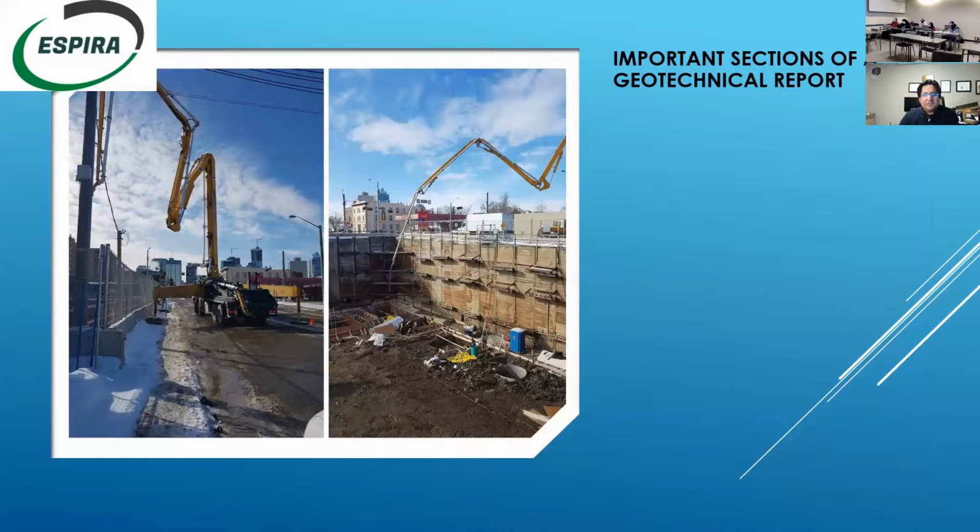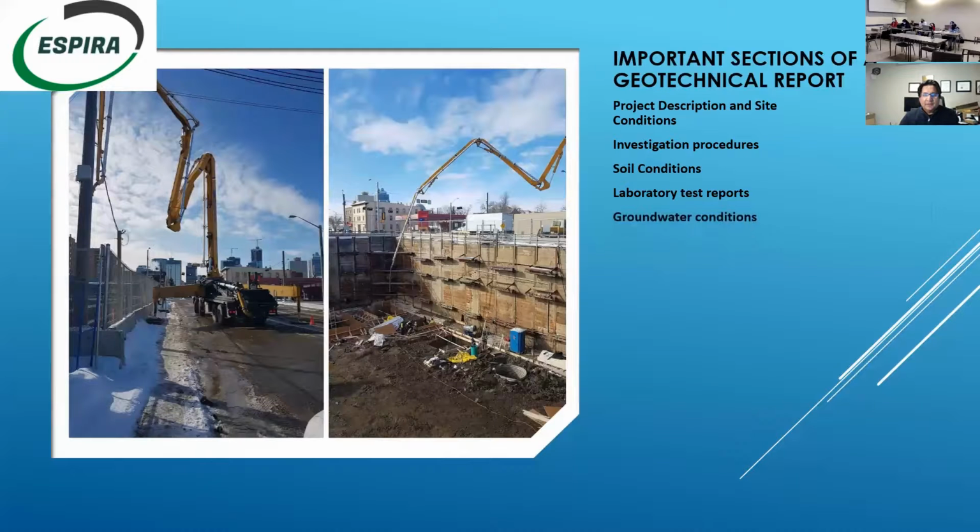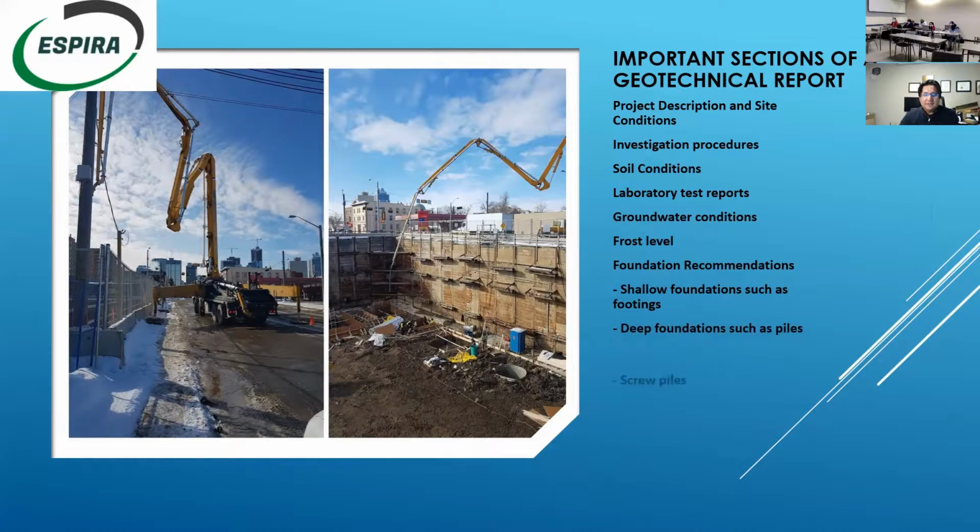Important sections of a geotechnical report. It should definitely have project description and site conditions, investigation procedures, soil conditions, lab test reports, groundwater conditions, frost level, foundation recommendations, shallow foundations such as footings, deep foundations such as piles, screw piles, pavements, earthworks, radon considerations.